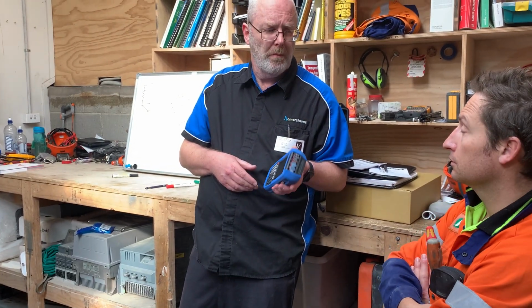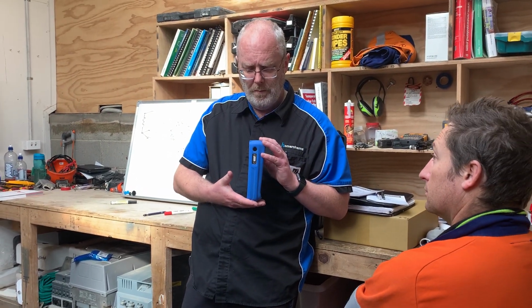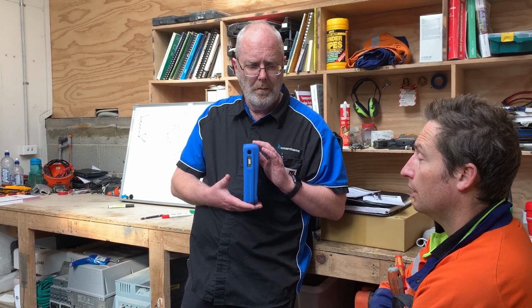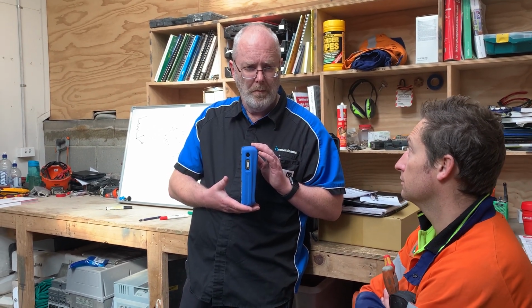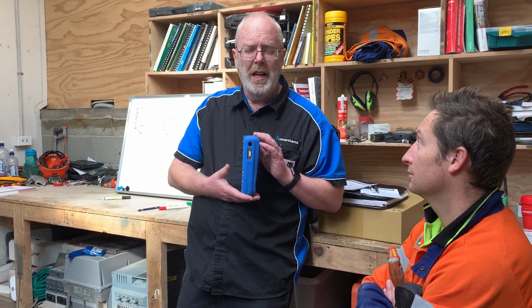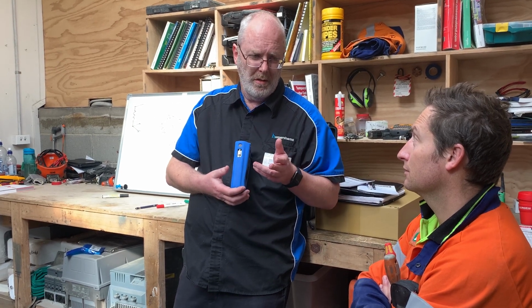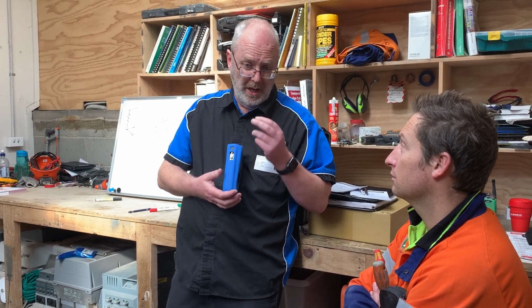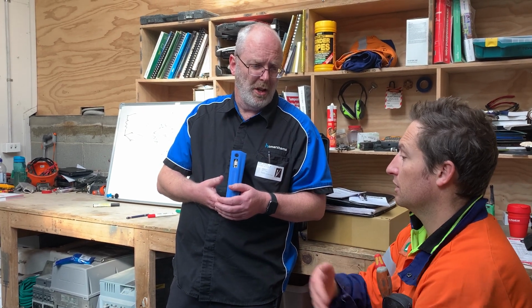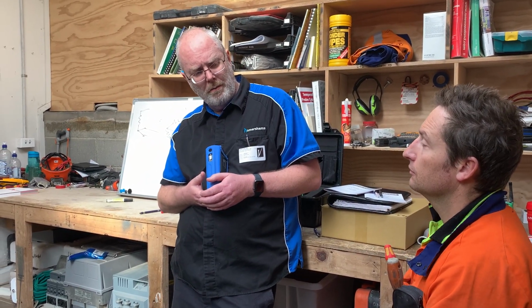Are there any applications that you might have that Greg's not covered? Can it confirm a flow rate? Not in an actual flow. It can confirm the pulses. What if it's 4 to 20 out? It will tell you the 4 to 20, but it can't confirm that it's so many litres. You can measure the current and you can simulate the current, but you can't convert that to a flow rate.